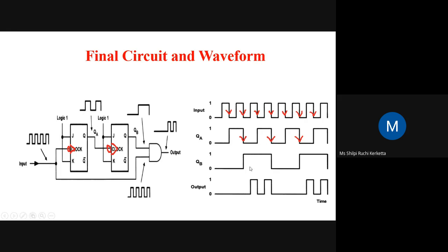So to make a delay of 2, we have used the output from this pulse as a clock for this pulse. So there is a delay of 2. So with first negative edge triggering, it is changing from 0 to 1. And for second negative edge triggering, it is changing from 1 to 0. Okay. And for third, it is changing from 0 to 1. So this is the signal. So this is the QB signal coming here, and we are taking this signal as direct signal.